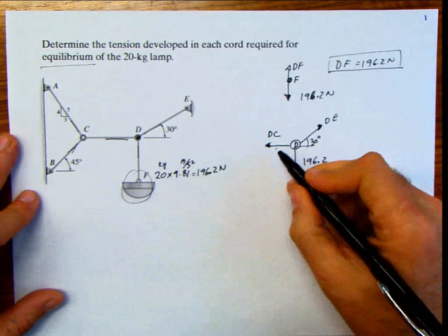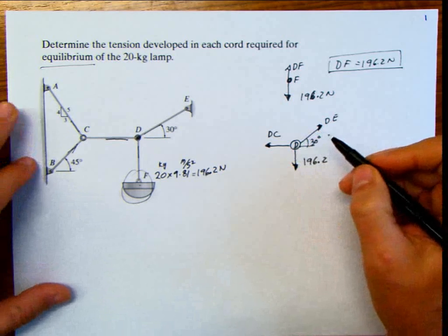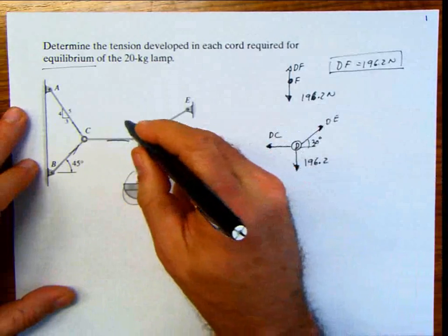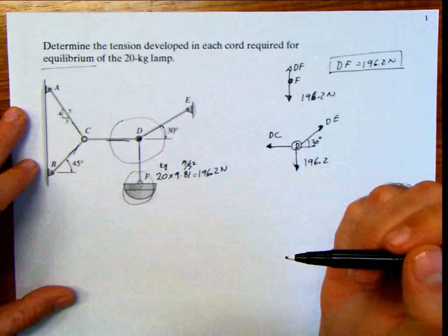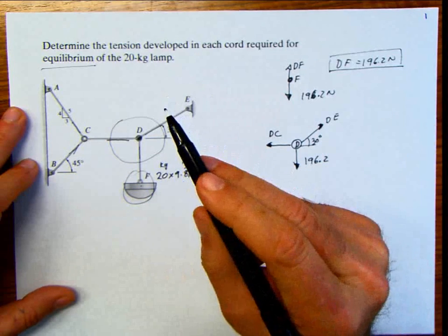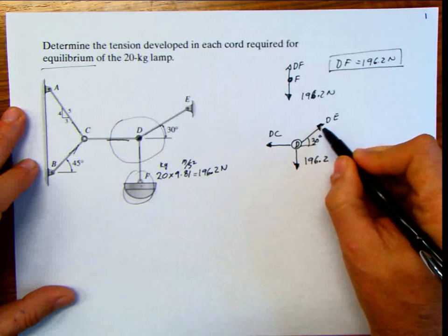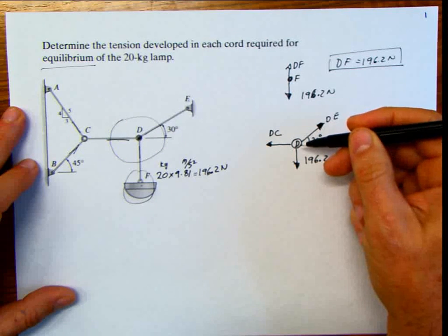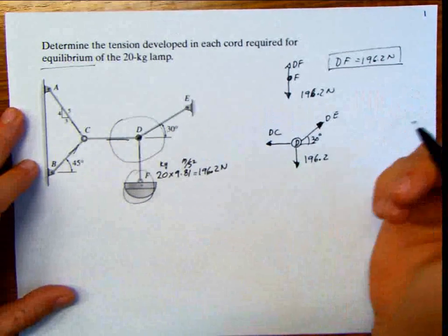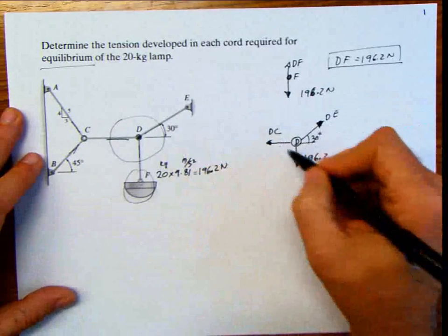There you go, one unknown, two unknowns. That means that we can solve this problem because we have two equations. One thing that I always say, when you do the free body diagram, remember you have to isolate this part and put every single force that is there, acting and reacting. Now, why do you put this force pointing up? Because it could come down. Why? Because these are cables, and cables don't push. Cables always pull. So the cable either is zero the tension or it pulls. That's why I put the forces going up.